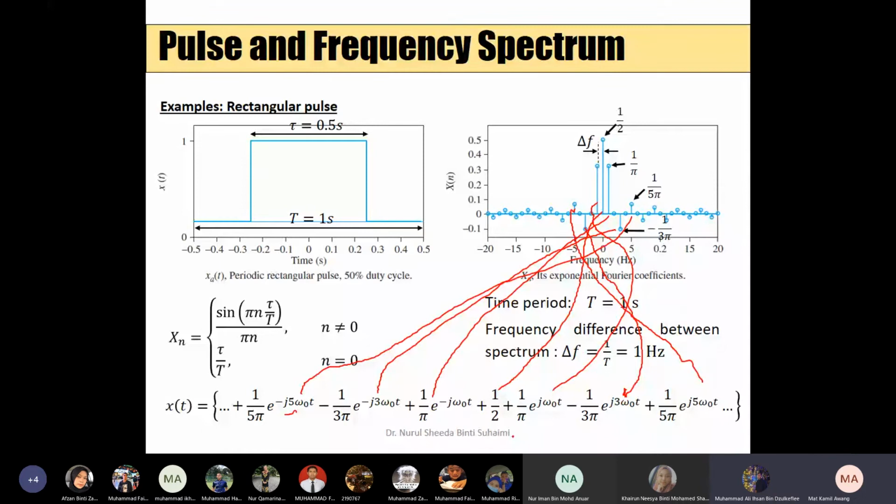Okay? So you can recognize this, you can plot on the frequency domain. Right? So this is actually the amplitude, the height of this. Right? Clear? Yeah. So the square wave, the rectangular wave, when you plot it on the frequency domain, you get something like this. So you get something like this, right? Which is like a sinc function, right? From last lecture.